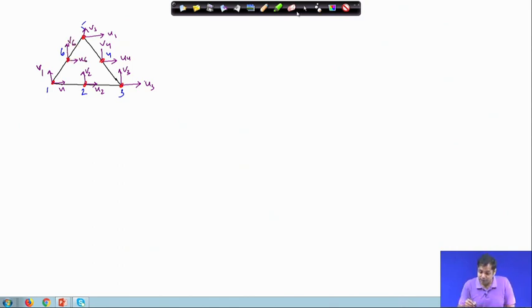Okay. Now, the general approach for whatever elements you are using will be the same. Now, you have 2 degrees of freedom here, U and V, which are independent displacement quantities, right. And U will be approximated as follows. Since you have 6 nodes here, we have information from 6 nodes. So, we can use, say, A plus Bx plus Cy plus Dx square plus Exy plus Fy square. We will shortly see, when we approximate a function through a polynomial, what are the terms to be considered.